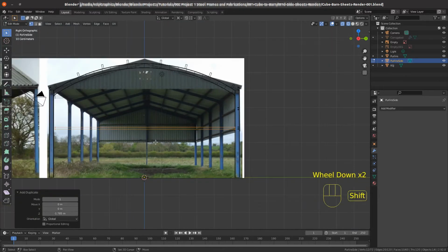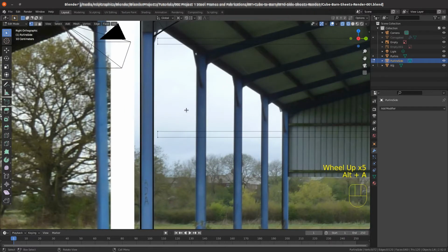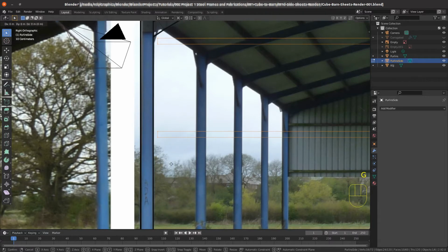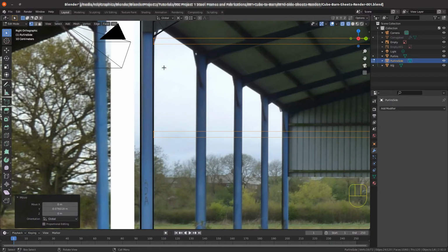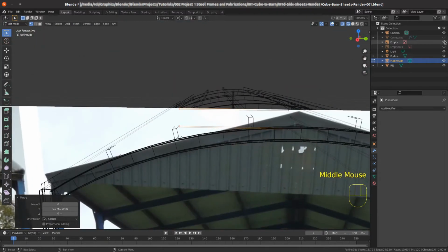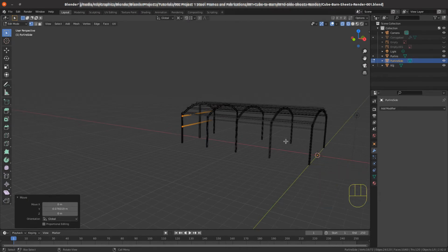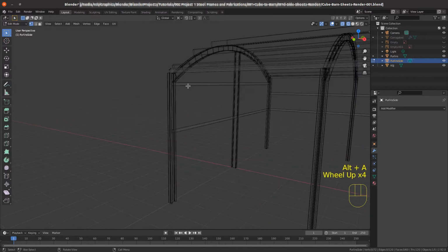I noticed on the right hand side they're not quite sitting up to the RSJ, so I'm going to Alt-A to deselect everything, box select the end of these purlins, and grab on the Y, and just take them across. We're not using snap at this point with magnet snap off. We could snap it directly onto there, but they wouldn't be tight up against there, they'd be on brackets anyway. So again, take the reference image out, and that now gives us the back and side purlins, and I'm going to just Alt-A to deselect that, so everything's deselected.